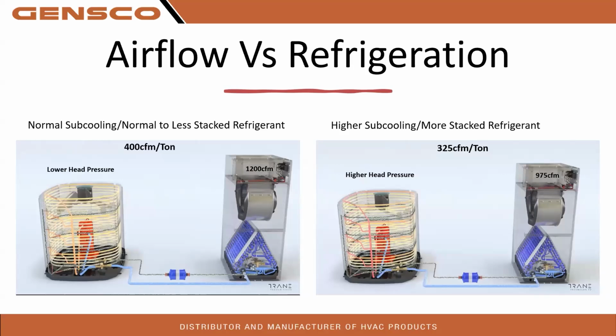Dry bulb is your typical supply return temps, what your thermostat sees, your sensible load. And you can actually do a calculation on what your total capacity is. Most of us will do a simple 1.08 times CFM times delta T. There's your sensible load, right? But without using wet bulb, you really can't find what your latent heat load is.